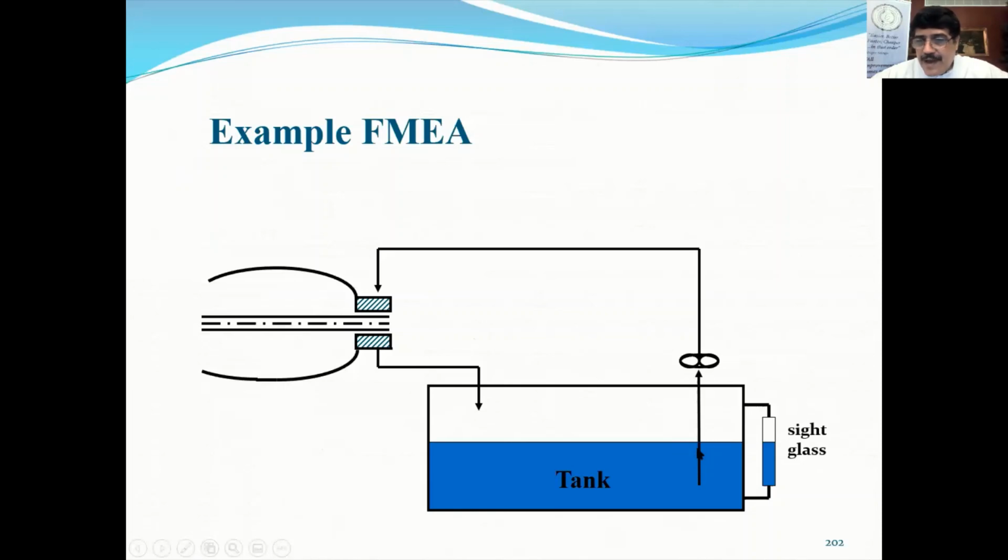And the lube oil tank basically takes the oil and sends it to the pump here, because the pump needs to be lubricated. But if we look at the tank only, the level in the tank has to be high enough. Otherwise, just like the oil in your car, if it's low on oil in the tank, it could create a lot of problems.